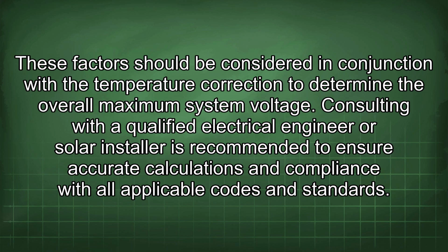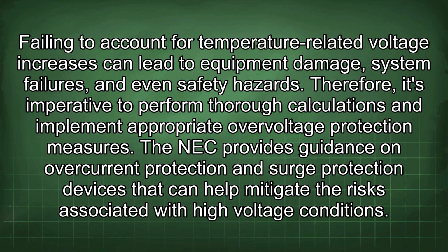Consulting with a qualified electrical engineer or solar installer is recommended to ensure accurate calculations and compliance with all applicable codes and standards. Failing to account for temperature-related voltage increases can lead to equipment damage, system failures, and even safety hazards. Therefore, it's imperative to perform thorough calculations and implement appropriate overvoltage protection measures.